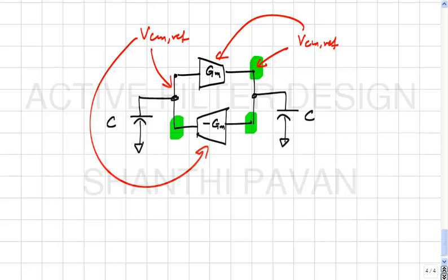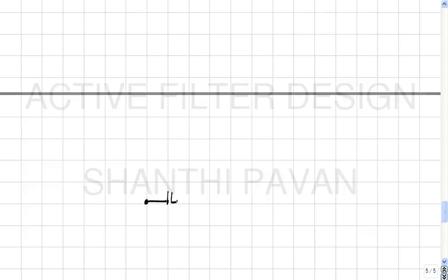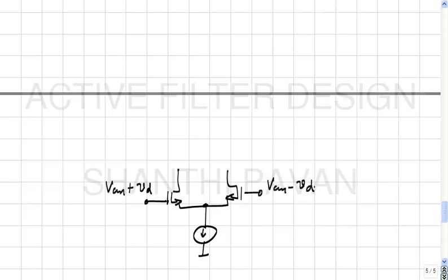So a common practice is to simply keep the output common mode the same as the input common mode. Okay. Right. So now our modified fully differential transconductor looks like this, and the output OP and OM is maintained at VCM also, correct? And under these circumstances, we have to make sure that all the transistors still remain in saturation.